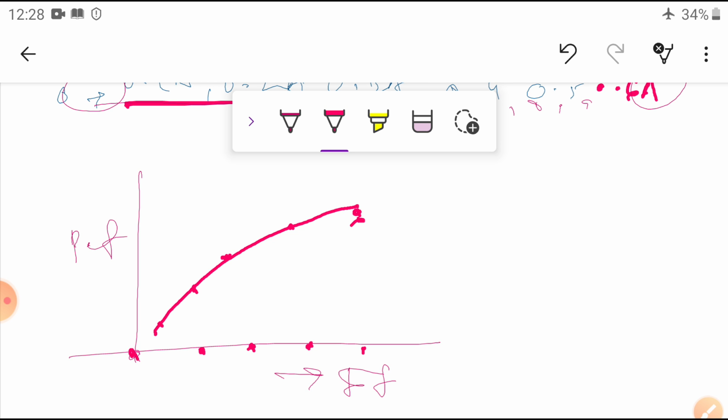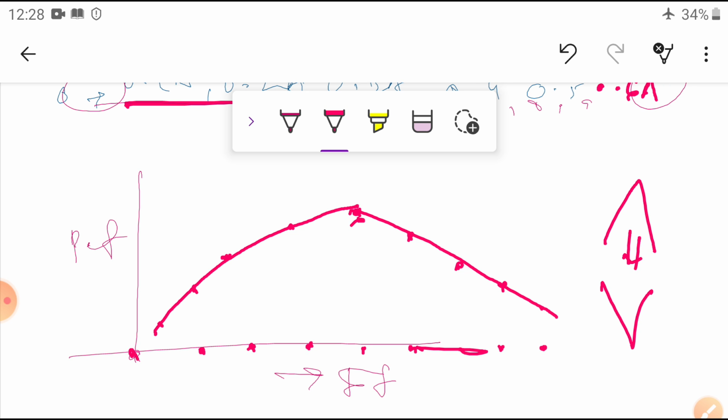Okay, based on this, if I increase the field current further, then our power factor is now decreasing. With further increase, it keeps decreasing. Then we get this curve. That means now we got an inverted V curve. This is a V shape, inverted. Instead of this one, it is inverted. So then we are going to test this.